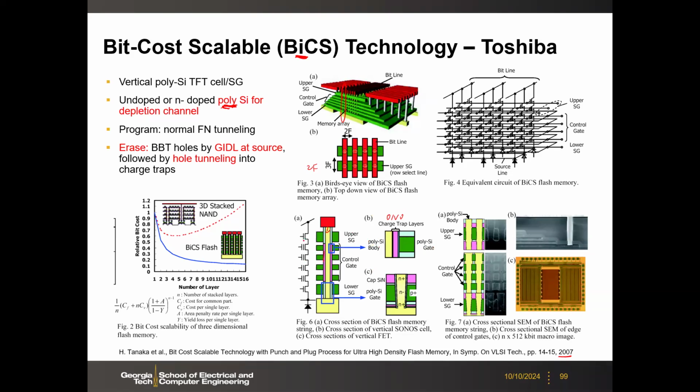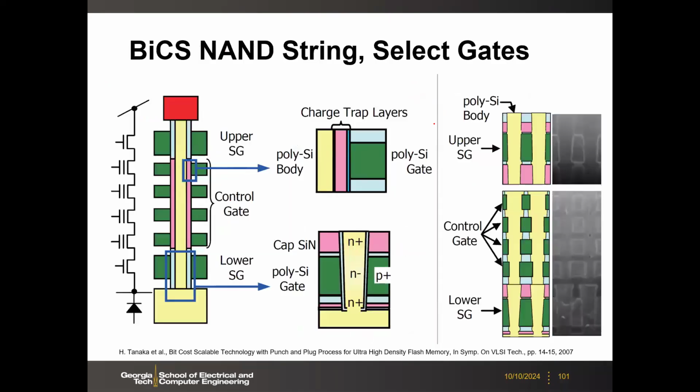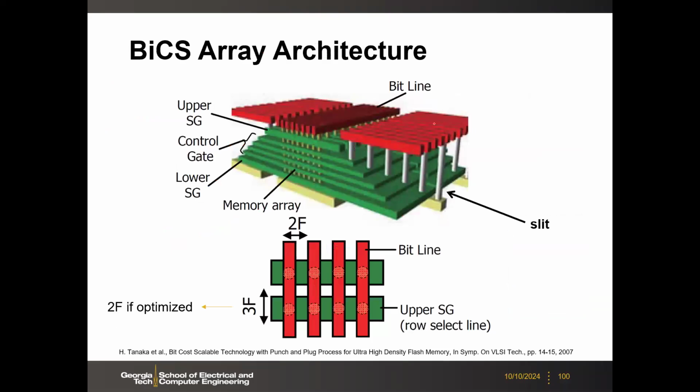Okay. So if you look at the schematic, and let's say net list, you have this string vertically. The top one is a string select, and the ground select. In the middle, you have those charge trap transistors in series. So this is just one string, but if you look at the 3D, then it's important to understand this 3D net list. Maybe I should have that in the next slide. Okay, we have some zoom in, so we can move to the next.